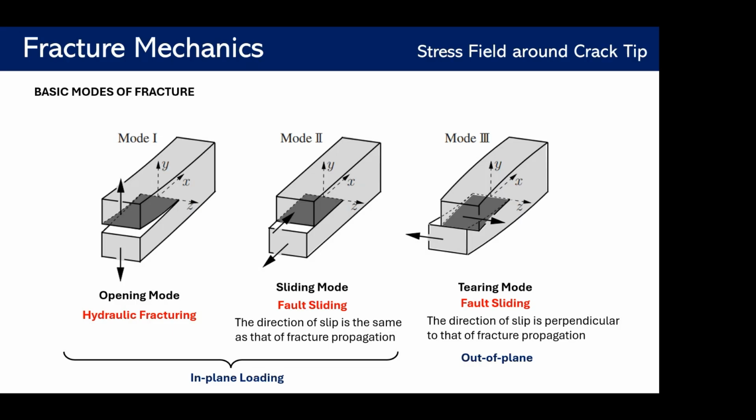I mean, the force in the z direction, normal to the xy plane. Any fracture problem can be decomposed into these three modes, and each mode can be analyzed separately, because we already know the exact solution for each mode.